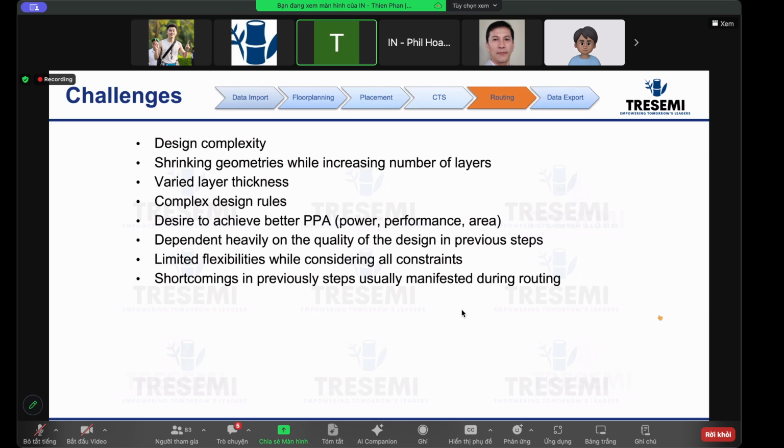It's not a real wire, but it has all the intention of where that wire is going to be. It has to assume the detail route will use that planning: I'm going to put a metal 2 here, using this track, exactly what layer and what track.